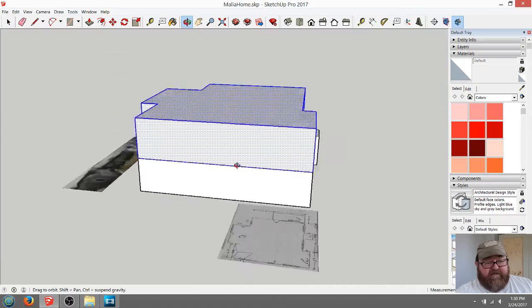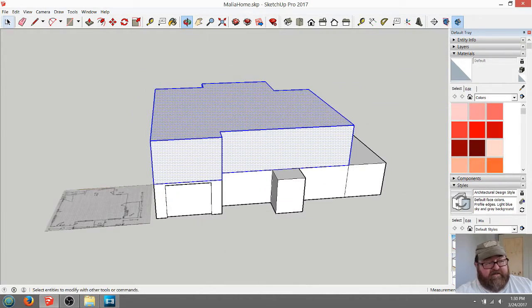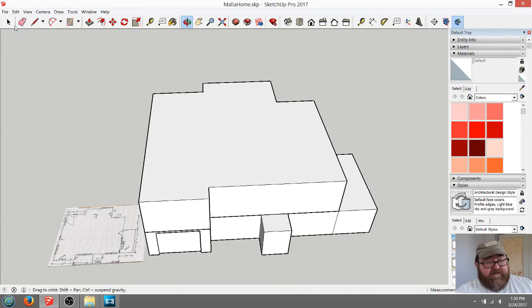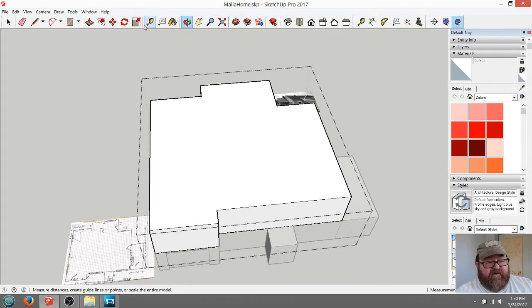And so now I have my main floor level, but I can also grab that. Make sure I'm not grabbing anything else. Yeah, I can grab that and create a block there, a group. I call it a block in AutoCAD. And now I can just work on that level. But a simple way to do this in SketchUp is there's this offset tool. Where is it? Right here.